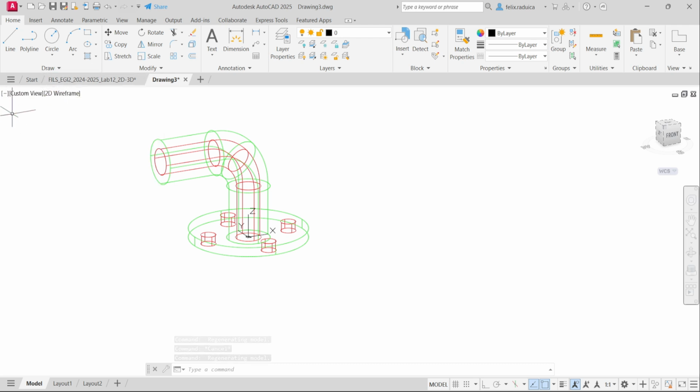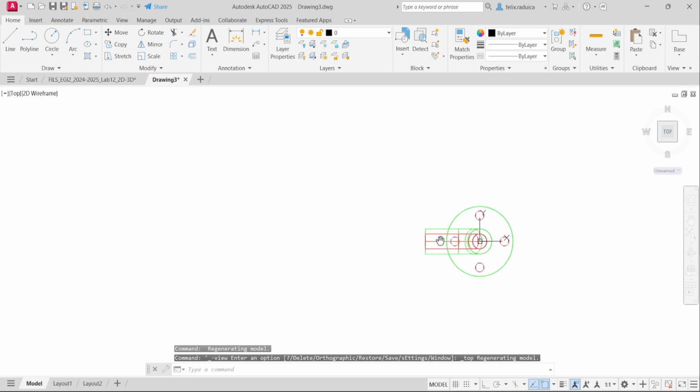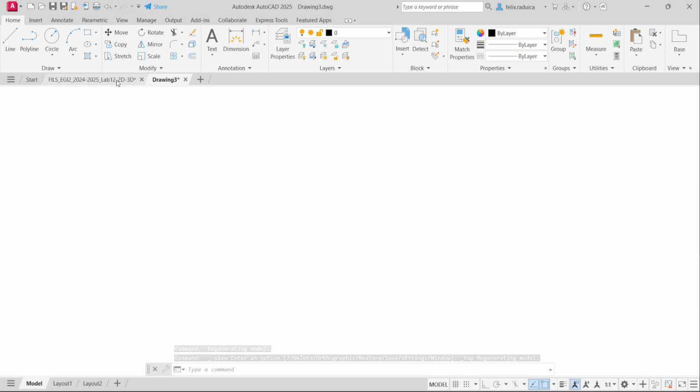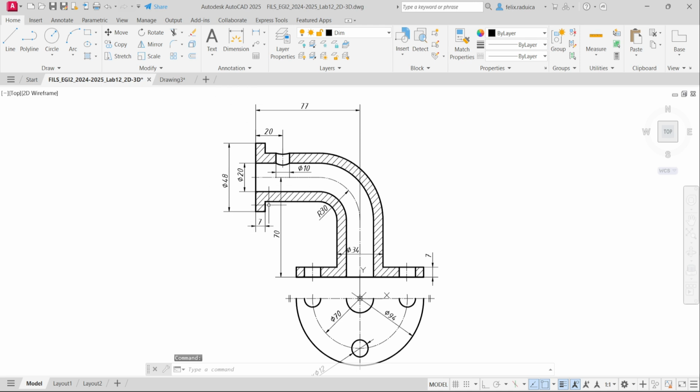I have one more thing to draw, actually two. So let's go to the top view here. And I have this ending here. And all I need to draw is this 48 millimeter diameter and extruded by 7. So I can create a cylinder and then attach it to the existing geometry. And when I subtract from all of the outside, this inside part, it will become a pipe part.